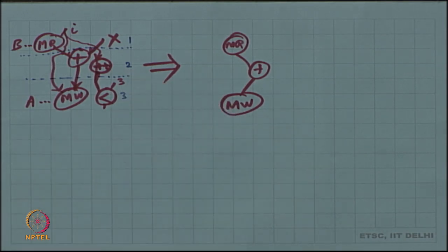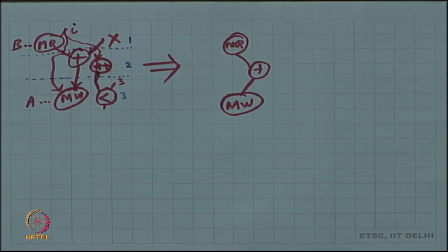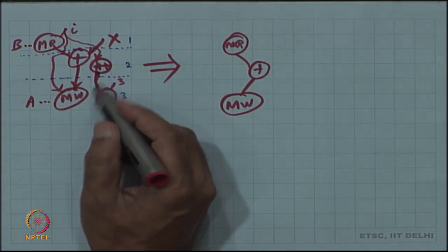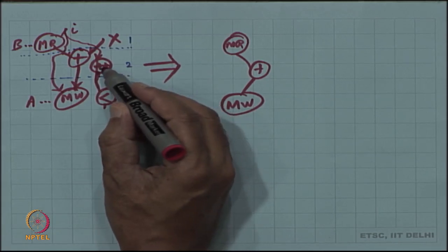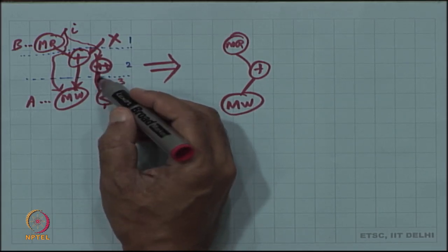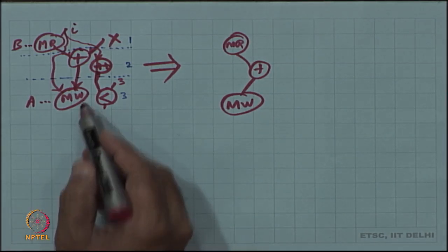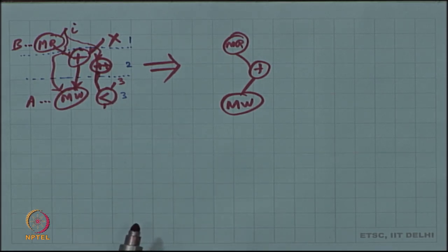So if we are sending the direct I, then the circuit should be fine. If this increment is actually changing the value of I right there, then there is a dependence that is created and you cannot have it later. But you could do it in a different way, where you do the increment here, but the result is stored in a temporary variable. You do need to update I at the end, maybe in the last cycle, but there is enough information for you to do the comparison.